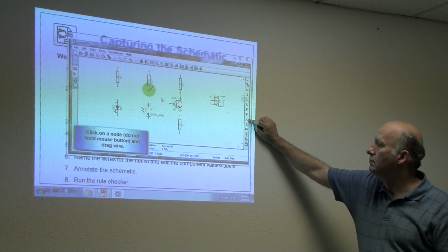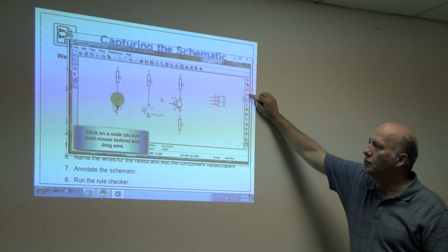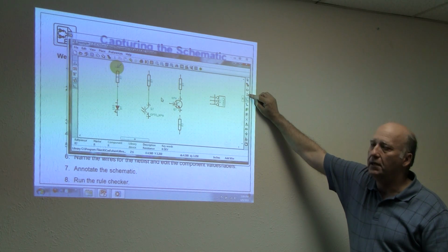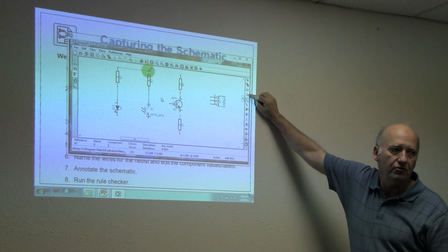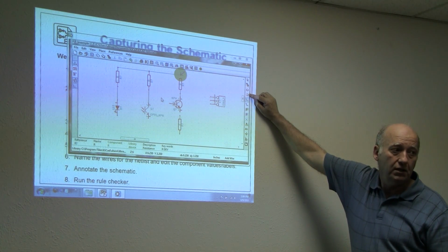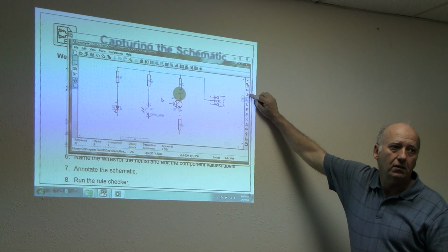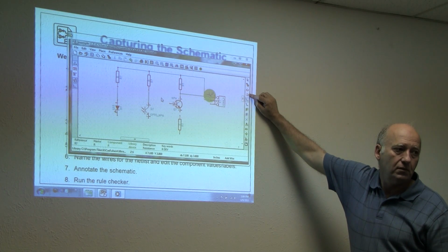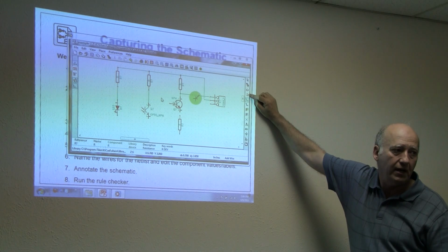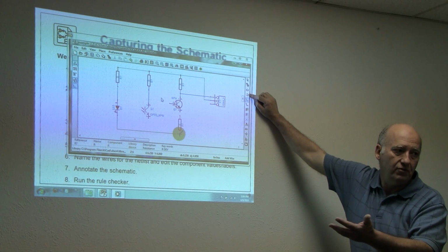What do you use that place a power port symbol for? The one, and this is the power port symbol, yeah, here. What do you use that for? Okay, let's say if you wanted something to be a power supply, like 5 volts, you would use this, okay? And there's also another thing, that if you had multiple pages of schematic that you call the power flag, which will take the power port and bring it onto the other pages.